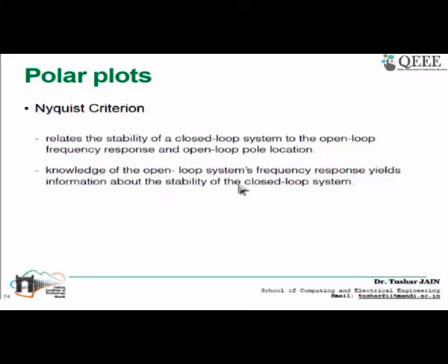What it does is relate the stability of the closed loop system to the open loop frequency response and the open loop pole locations. We'll see this point in detail. The knowledge of the open loop system frequency response yields information about the stability of the closed loop system.